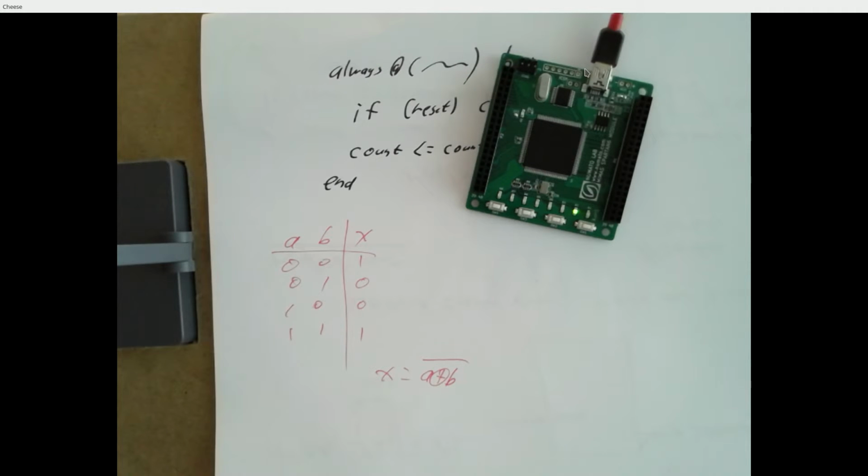You can also simulate it in the Xilinx tools. And there's a section in the Mimas board documentation that tells you how to set up a test bench in the Xilinx tool chain, right? And you basically say a new module, you say you want a test bench, you tell it which module you're testing, and it sets up a framework for you, and you just drop in your input stimulators and go ahead and run it.